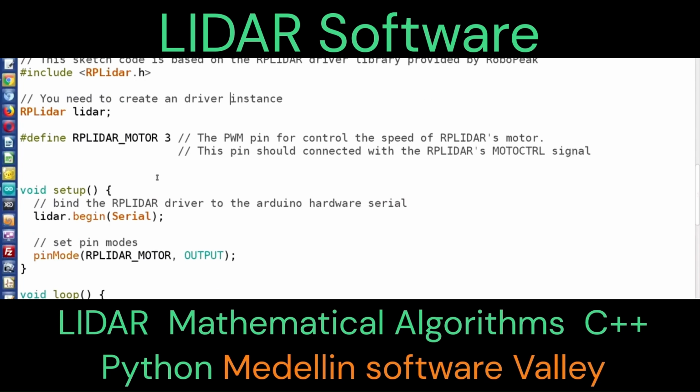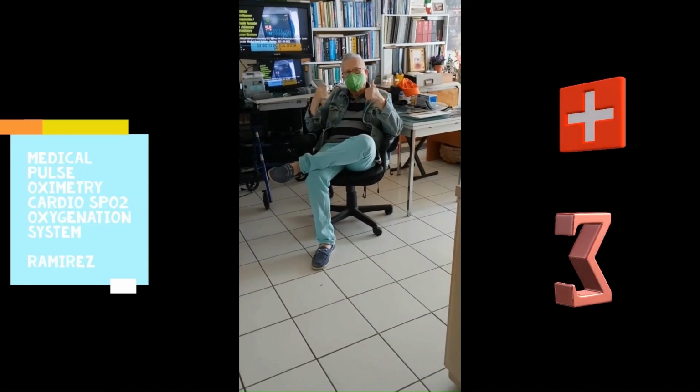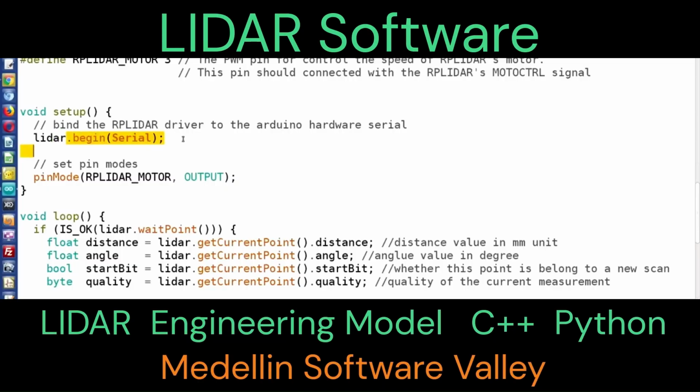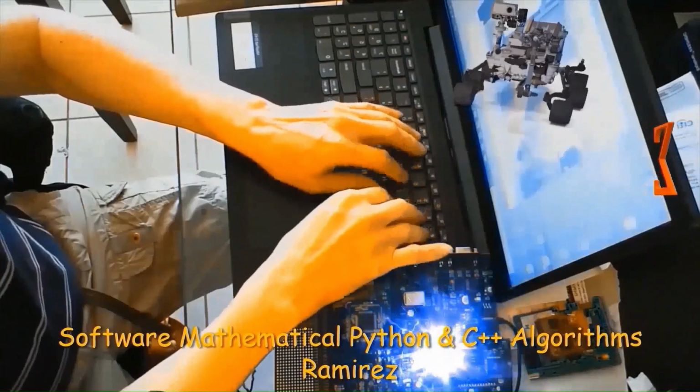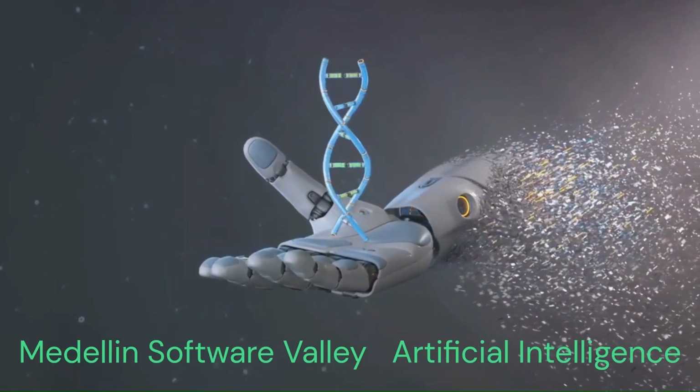The current signal is converted to a voltage by a transimpedance amplifier, the TIA, which is typically implemented as a discrete component outside of the system-on-chip architecture. The interface between the photodiode and the TIA, the transimpedance amplifier, is critical because it impacts the LIDAR range precision.